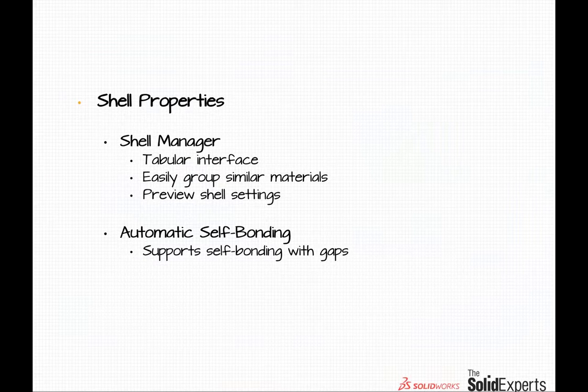Some of you may have noticed that SolidWorks is trying to improve the user interface in a lot of the simulation parameters windows. This is a case of that, where you're going to have a tabular interface now that gives you a nice little table at the bottom of your screen that allows you to manage all of your shell definitions live, which is much more convenient for a user to be able to see what's going on as opposed to having to drill down through the feature manager and check on each shell property individually.